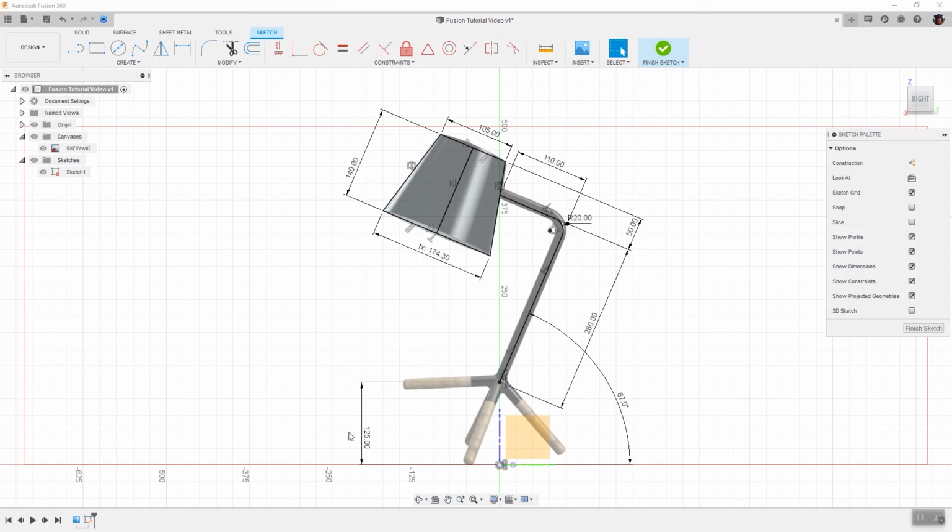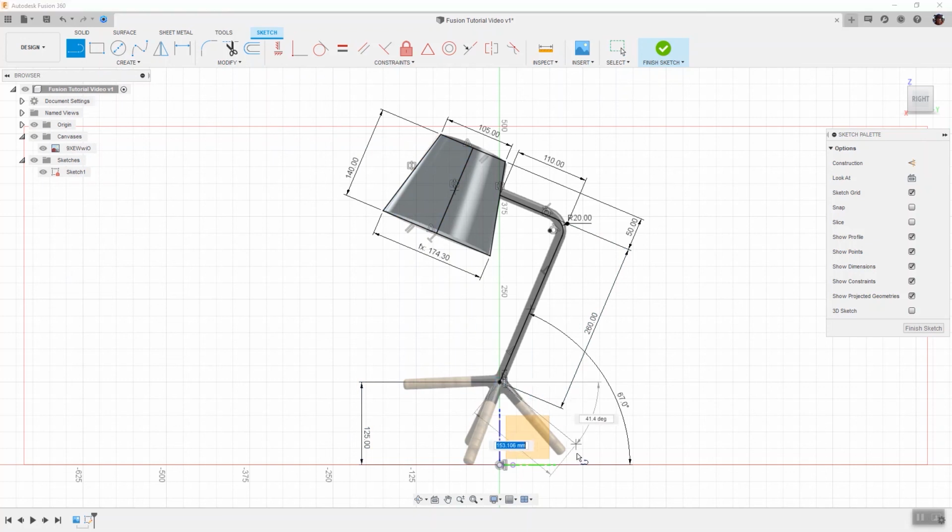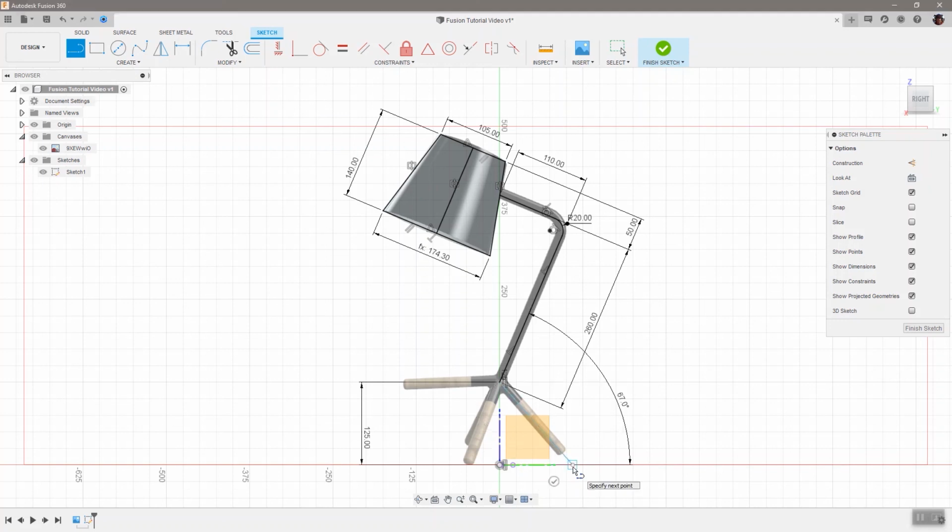We can do this very simply just by Create, Line, and then going from this point down to the origin, snapping to that again, and then pulling it out. Keep in mind that the picture here has a short leg because the picture is taken with a perspective view, so that back leg will appear shorter in our picture.